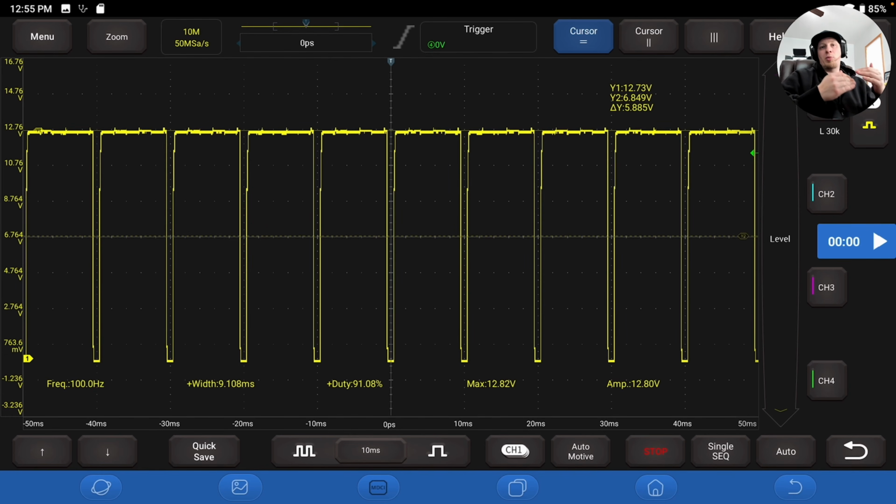Plus minus 10%, because the circuit is operating normally. So now we know, after doing our loaded voltage drop test, comparing the left front and the right front, and also looking at the signal with the scope, that the left front, all the wiring and connections are okay, the ground wire is good, the power supply is good, all the connectors are okay, everything is fine on the circuit. The only problem we have is a burned out bulb.